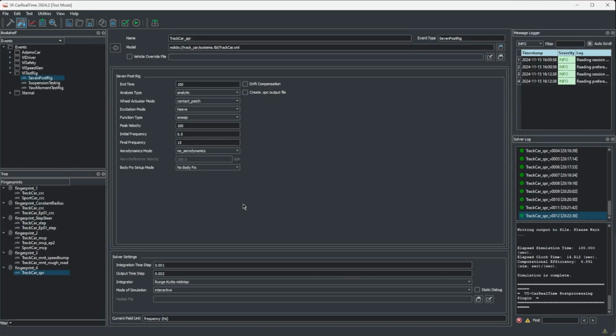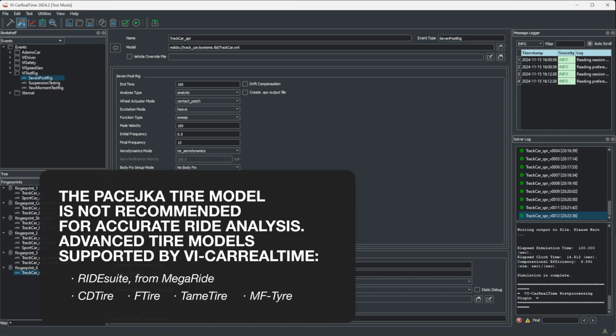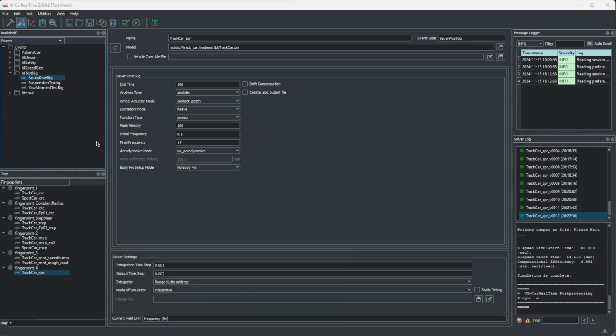We will now set up an investigation where the car will perform this test with the selection of dampers options. Based on experience, we can define the initial range of damping ratio we want to cover. That will likely include the optimal damping for load variation and the optimal damping for height stability. These new dampers are ready to use, with no need for the scaling factors we applied to our original components.